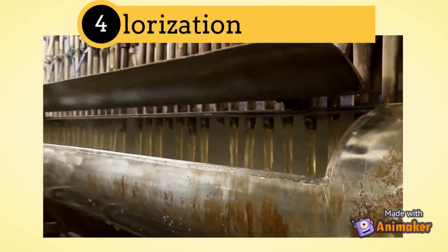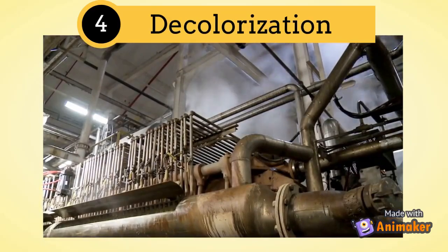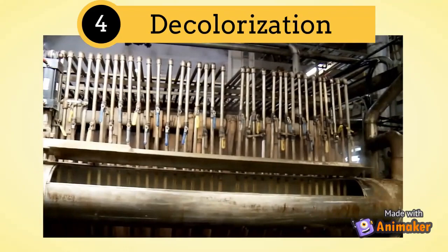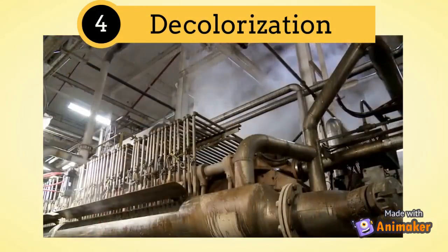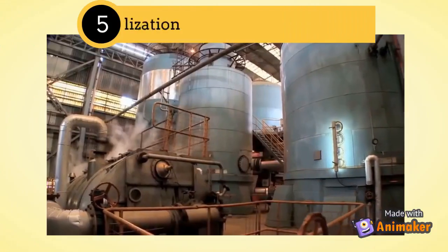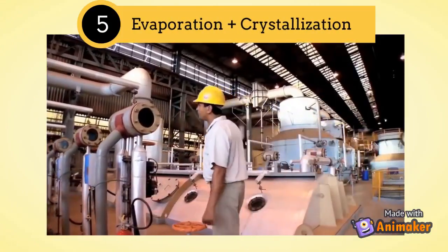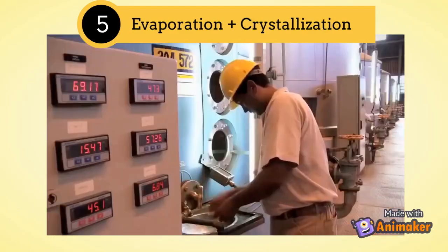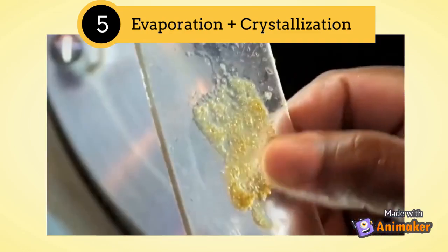The clarified sugar is filtered to produce a pale yellow liquor. To decolorize this, adsorbents such as granular activated carbon and bone char are used. In this process, soluble impurities are also removed. The decolorized sugar liquor undergoes the same evaporation and crystallization processes used in extracting the raw sugar. However, this time, these series of processes result in a refined sugar.